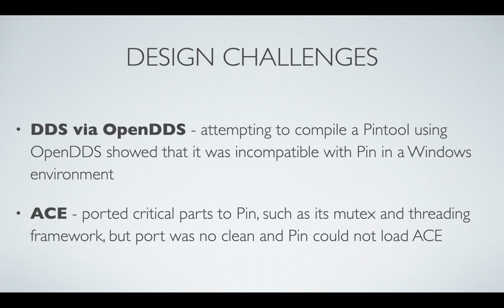So several design challenges that we faced, and you'll see why we ended up going to the BISON approach, is that we wanted to leverage some existing technologies that are already used in real-time embedded systems, distributed systems, and so forth. One was DDS, and we tried to do it with OpenDDS. One of the challenges we found with OpenDDS was that when we tried to compile OpenDDS into a Pin tool, it wasn't compatible in a Windows environment.